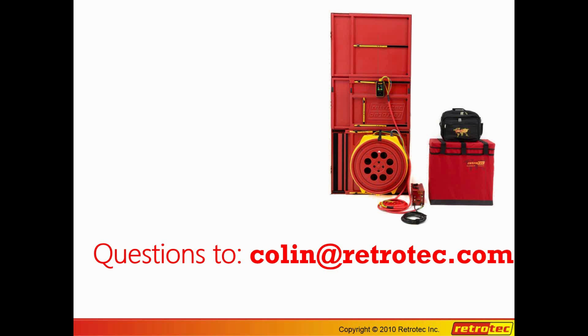So a person was asking where the best place for the PRV is. The pressure relief vents, or PRVs, are best installed as high up as possible. The reason for that is when the agent is being discharged, and if there is any pressure in the room, it will tend to force air out of the vents and not agent. So that tends to work quite well. The other thing is that they won't add to agent loss when you're in the hold time phase.